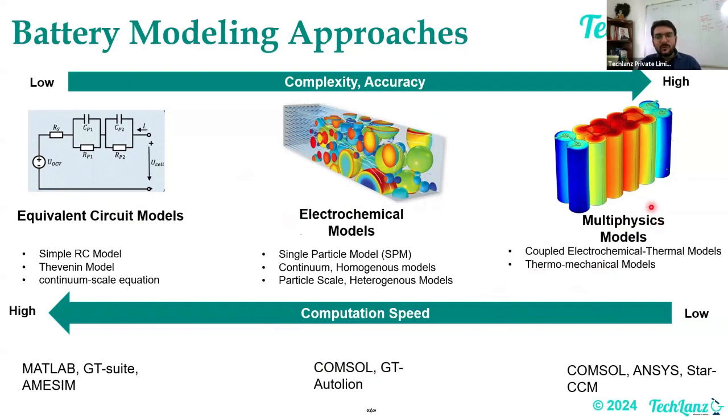Suppose you want crash simulations, or you want to understand thermal runaway, like the thermal runaway experiment, the puncture test, which is the nail penetration test. That time you need these kinds of models, because in the nail penetration test you have a mechanical boundary of the cell, where the mechanical properties decide how much strength or resistance my mechanical structure offers to the nail while entering, how deep it goes, and how it is breaking the layers. So that's a multi-physics model.